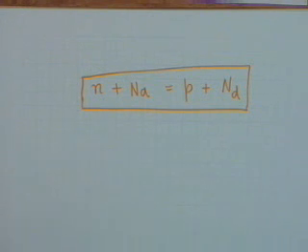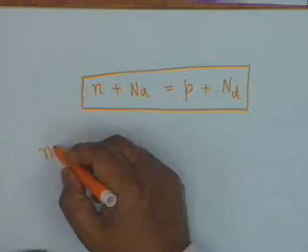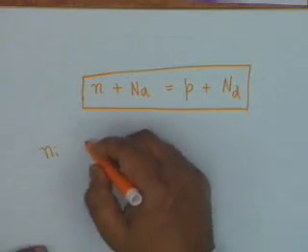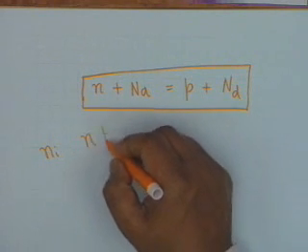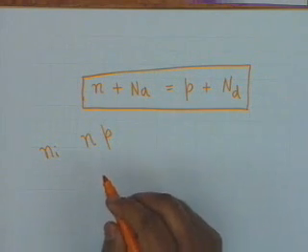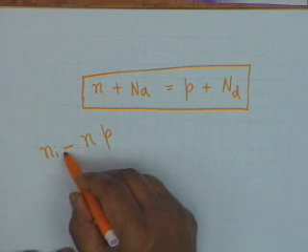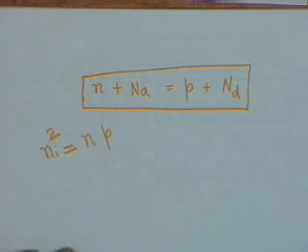Now, when you disturb the balance of holes and electrons by doping, there is a certain relationship which holds between the intrinsic concentration Ni and the concentrations of n and p as a result of doping, and we shall show that the product is a constant equal to the square of Ni.